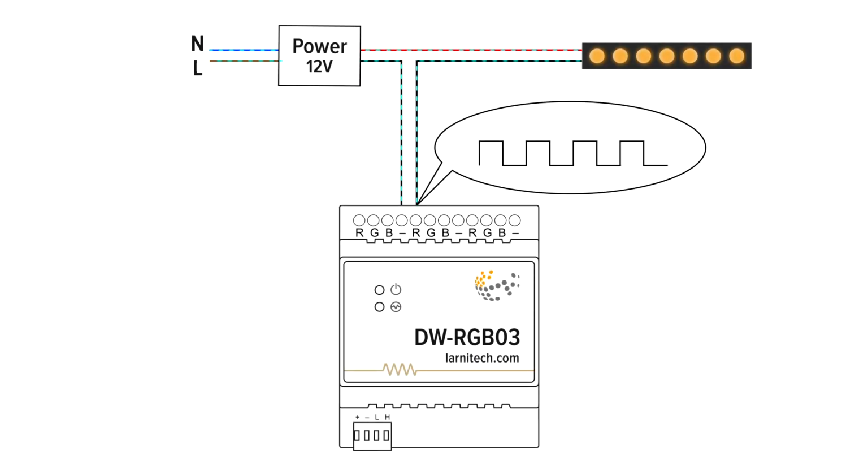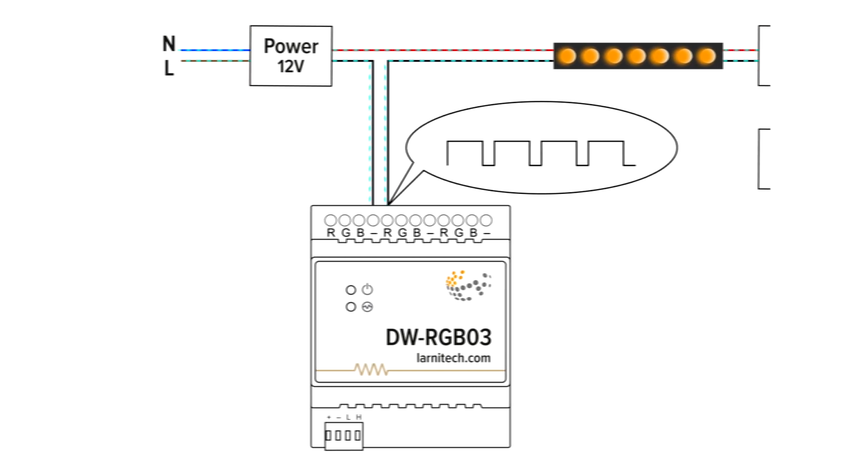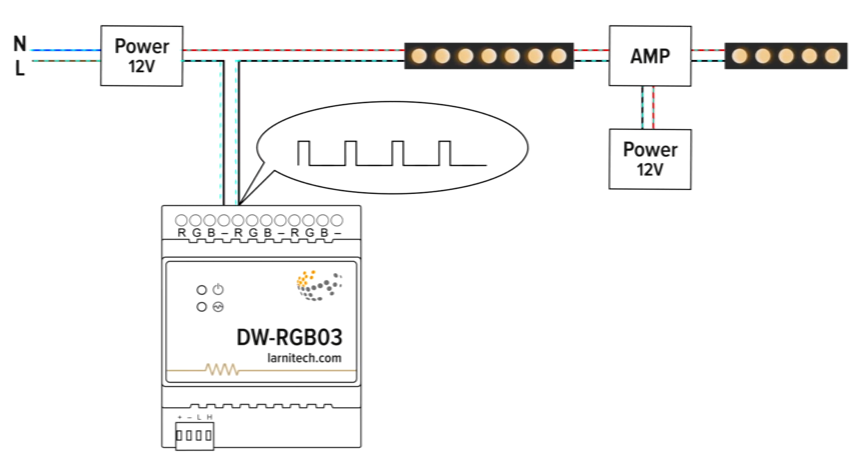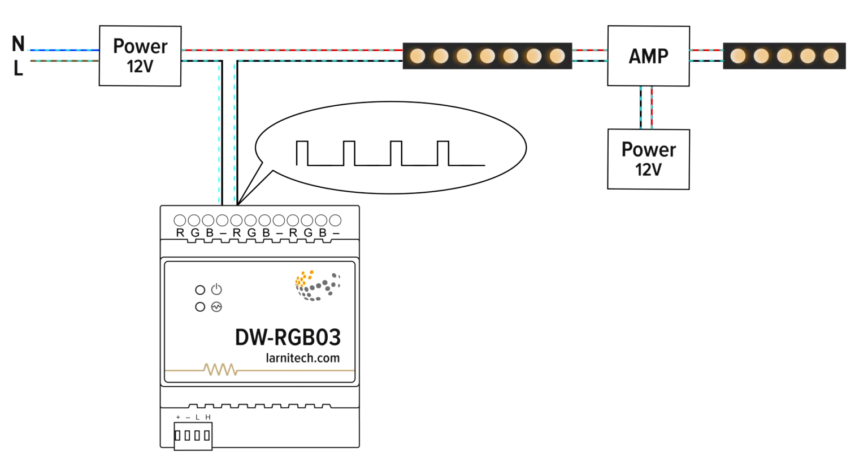For dimming lighting or backlighting operating on 12 or 24 volts DC, PWM outputs are used. A PWM output contains an electronic switch that closes and opens the circuit 400 times per second. By adjusting the duration of voltage supply and absence, the brightness of the lighting can be changed. If the power of the PWM output is insufficient for connecting the load, additional current amplifiers are required.